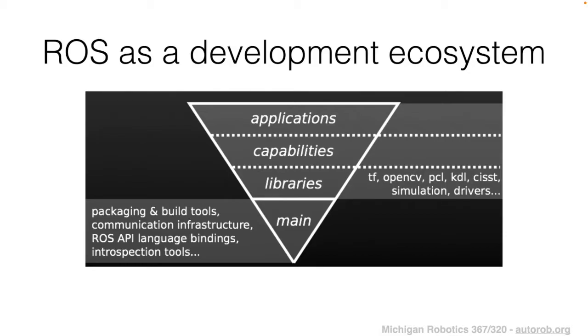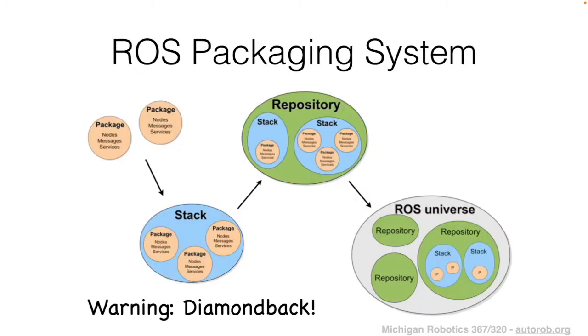And then the ROS packaging system provides an API to ensure that your application is developed in a way that is standardized for its communication with other nodes within ROS, and also for distribution as a proper ROS package. If we look at what that ROS packaging looks like, this slide illustrates the core components that go into ROS packaging.